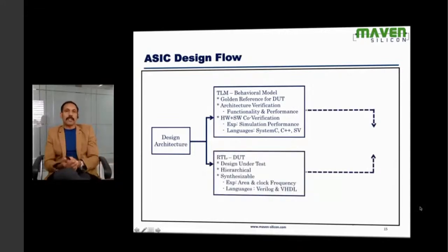Then later on, obviously, the design team is going to create RTL. The RTL will have different kinds of goals related to synthesis. They might be looking at various things like area and clock frequency, and basically the design team uses languages like Verilog and VHDL. But if you look at TLM, the modeling engineers always use languages like SystemC, C++, and SystemVerilog, non-synthesizable model. And during verification, this TLM is going to act like golden reference model.